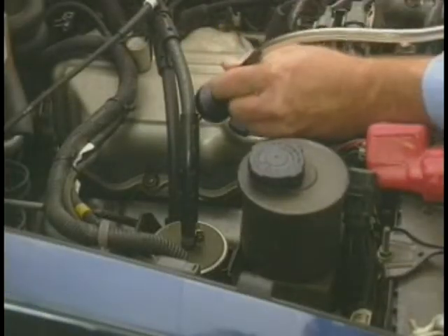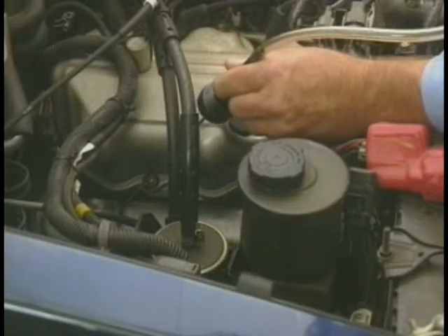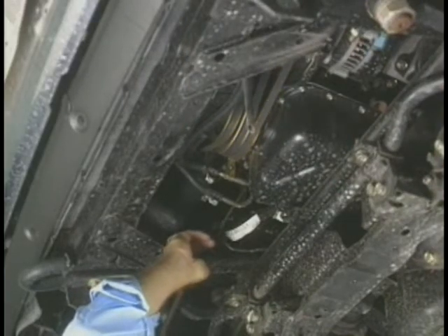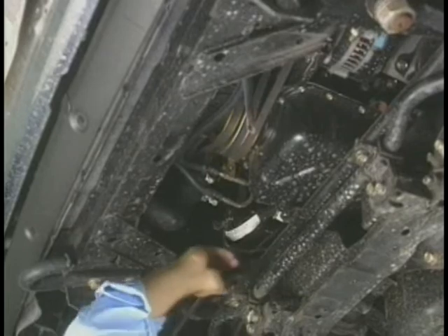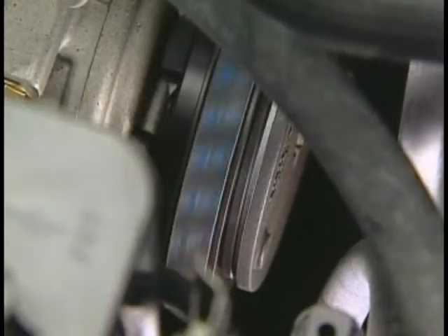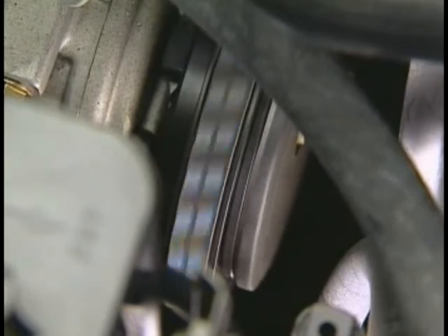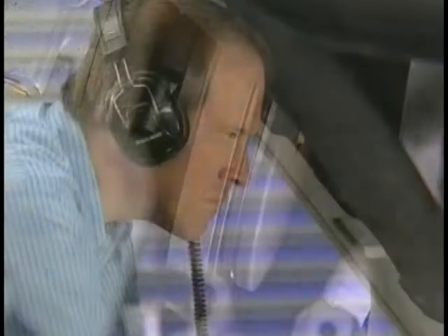If there's a knocking noise as the compressor is operating, the system may be overcharged. A slapping noise usually results from a loose drive belt or bent pulley. Faulty compressor clutch bearings will make a growling noise when the clutch is engaged and the bearing is loaded.